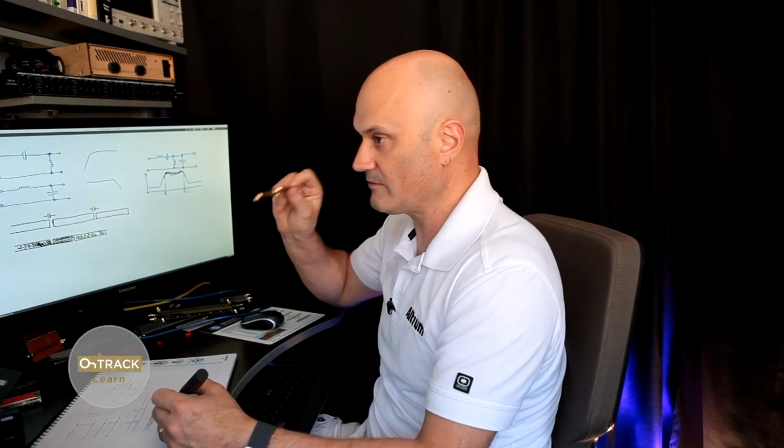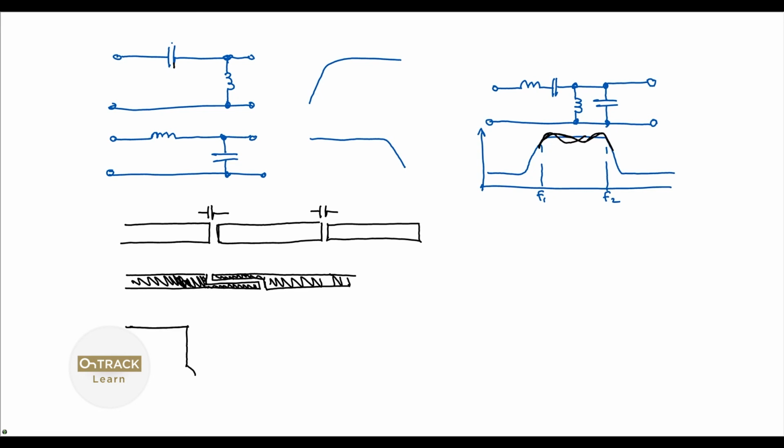Now remember, in the last episode, we were talking about couplers, and we looked at our 90-degree hybrids to start with, but we ended up looking at directional couplers which use electromagnetic coupling. And that's, again, where you have transmission line segments that come close to each other for a quarter wavelength or more. They're pretty broadband devices, actually. So you can have this kind of thing.